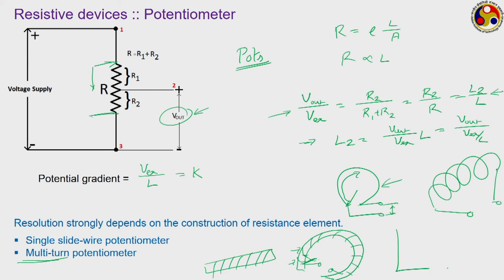So, the change in the resistive value is more like a staircase, but the height of each of the stairs can be kept very small, to a negligible amount, by choosing a proper resistor coil and also choosing this particular dimension of the pad suitably.